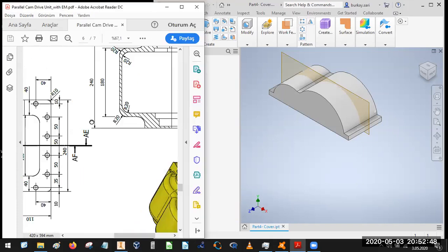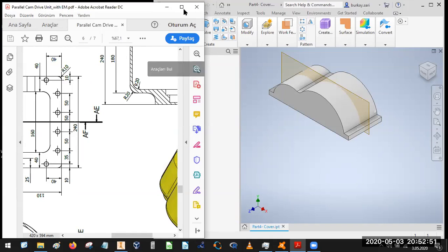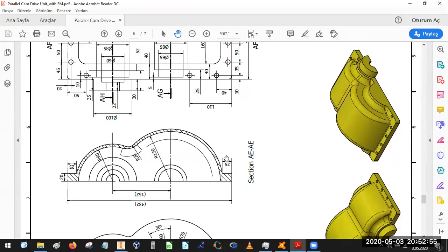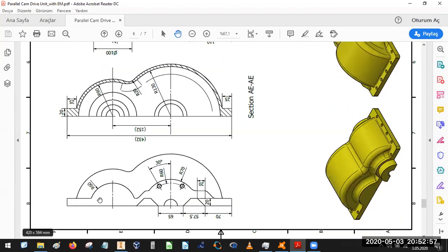I will make the extensions. What are those extensions? From the outside views, I will take this view as outside. As you see, we have a fillet arc shape here, having the radius of 60. We have also another arc shape, which is 70, and it will follow the outline here. First, I'm going to make this portion in my figure.